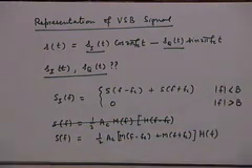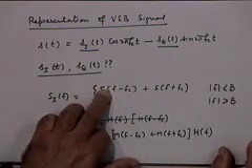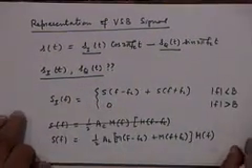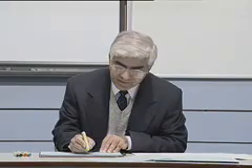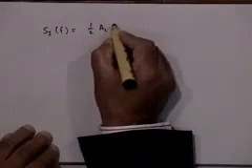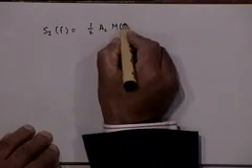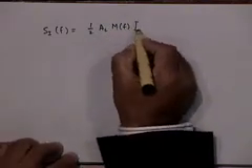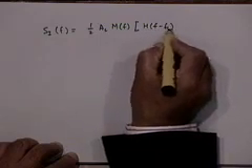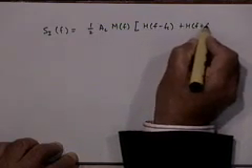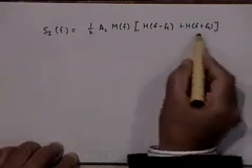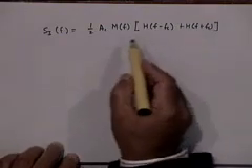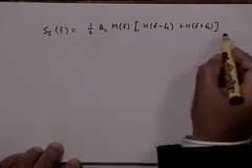The other 2 terms were around 2fc, right? So if you substitute that here, you get 4 terms, 2 of which are in the baseband, and it is those 2 terms which you need to look at. If you recollect, it is in fact obvious, it will be half A_c M(f) into [H(f − fc) + H(f + fc)]. In fact, it is from this point that we derived a requirement that this should be equal to a constant, right?